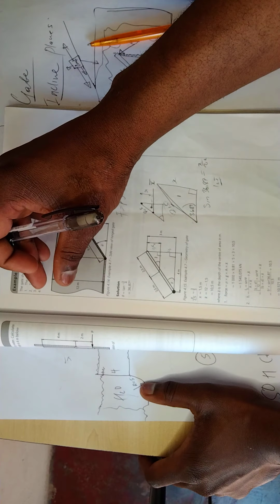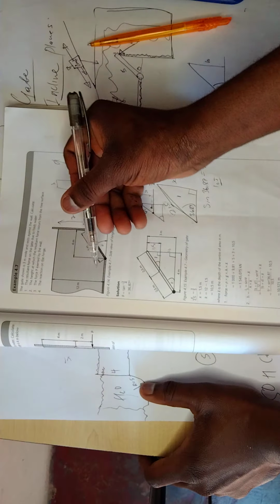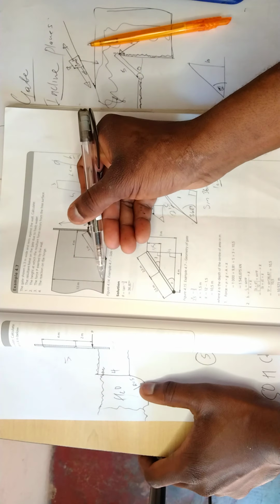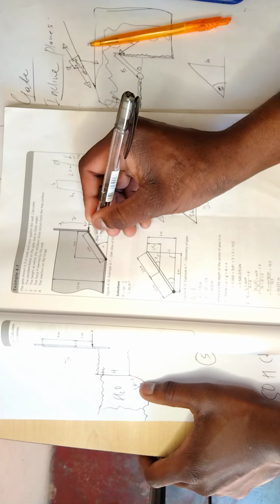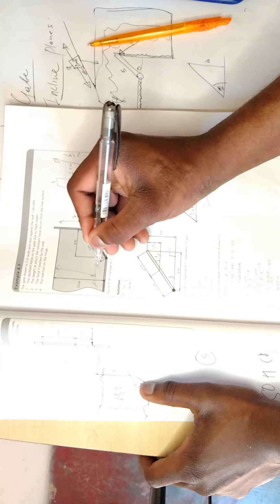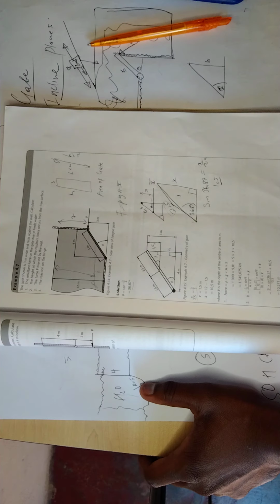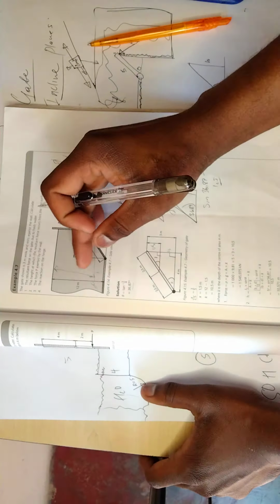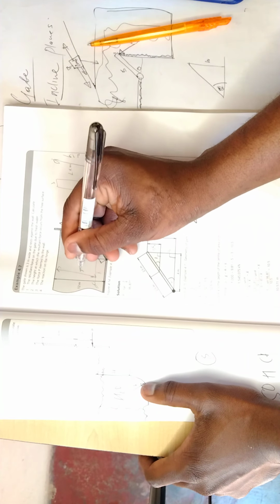The real centroid will come from subtracting the total amount, because it's from the bottom. Can you see? This is from bottom to top, so we need this here. The centroid actually will act from here going up, so we need to subtract this value, which is going to be 1.5. So we're going to say 12 minus 1.5 is going to give us this X bar.